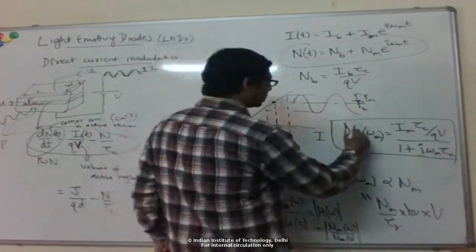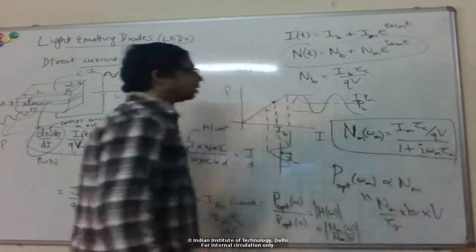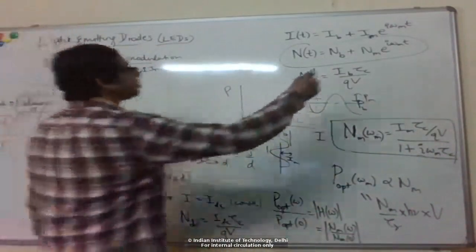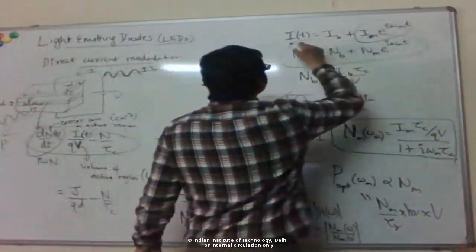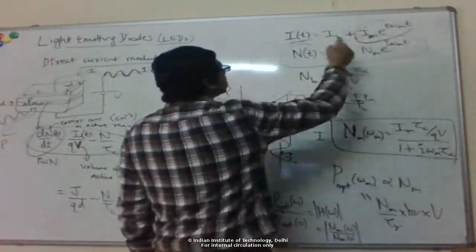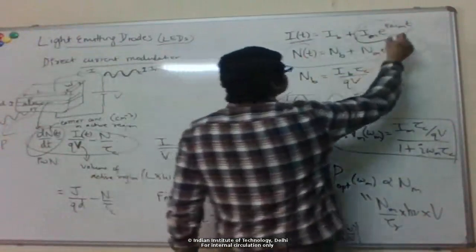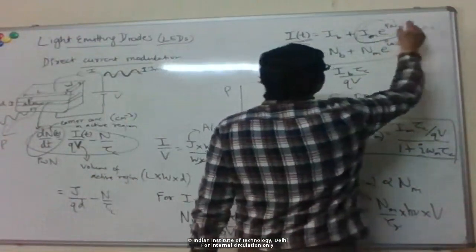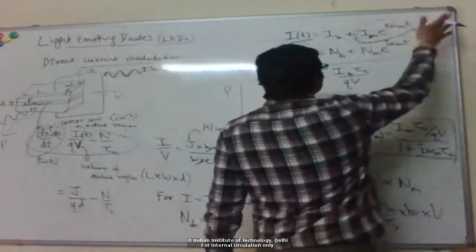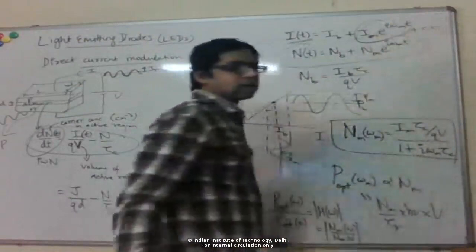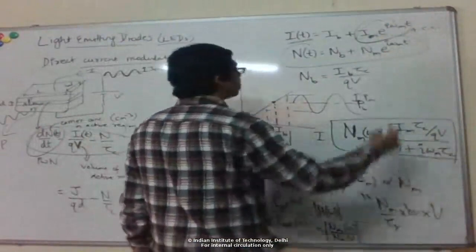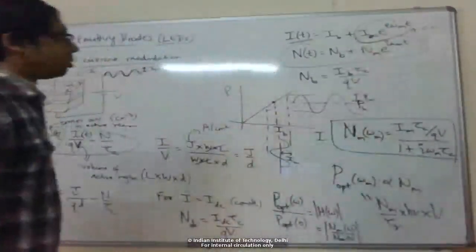Because now n, recall, is a complex number. So what does a complex number for a carrier concentration mean? Again, it's because we are writing quantities as complex phasors, right? Of course, current is also not complex; it's real, so the actual real current is the real part. So you add the complex conjugate to get a real number. But just for ease of mathematics, for complex phasors, we just ignore the conjugate part. So that's why this is a complex number, because we're dealing in terms of complex phasors.